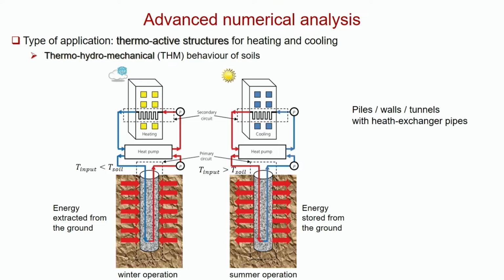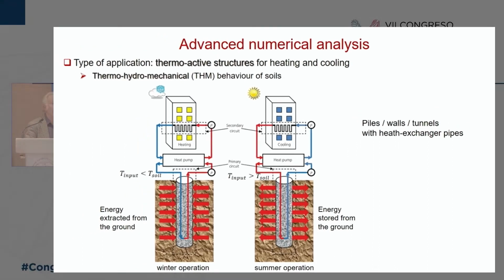It goes in colder. The soil heats it up. It comes out. It goes into our heat pump. The heat pump extracts it and perhaps increases the temperature by compressing it, and it goes through our building, heats our building up, comes back down here and goes through again. Meanwhile, here the cold water, the heat's been taken out of it, it goes back and gets heated up.